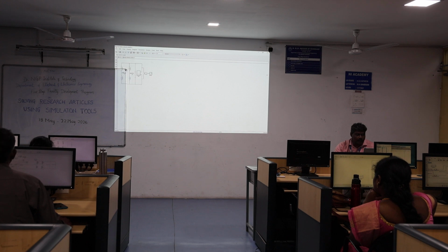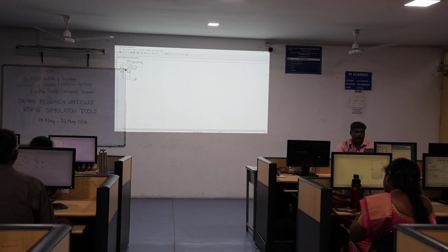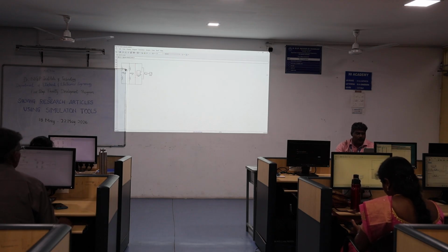So we are automatically changing the load disturbance. Even though we are changing the load disturbance, our output voltage should be maintained constant. Okay, so that's why we are doing this arrangement. So this switch arrangement, double switch, again timer. So one load is connected from 0 to 5 second. After 5 second up to stop time 15 second, 25 ohm resistance is connected. So this is the load variation.